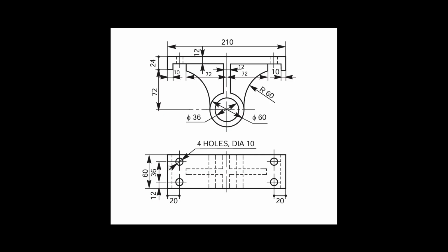What does it represent, and how can we use this to create a 3D model in SolidWorks? Look at the dimensions from both the front view as well as the top view. Using only this, we are going to draw a profile and create a solid body from that. Also, we just transfer this body to create these portions also.